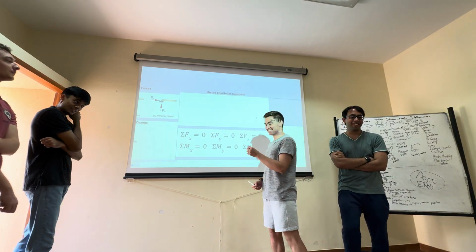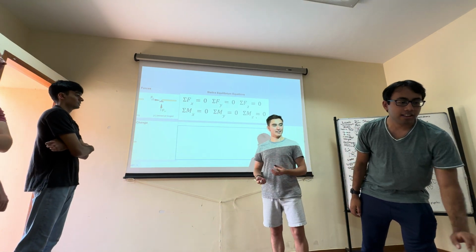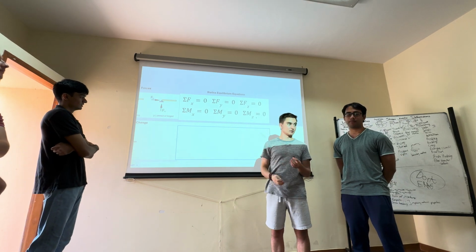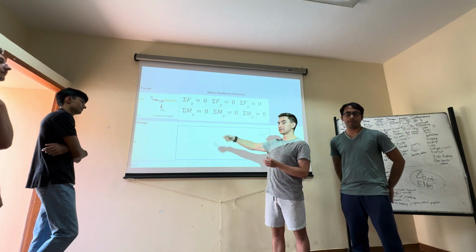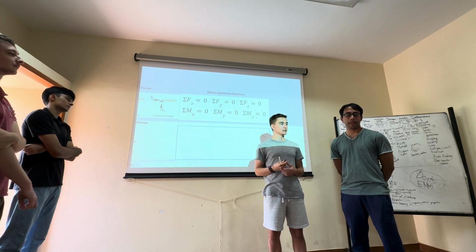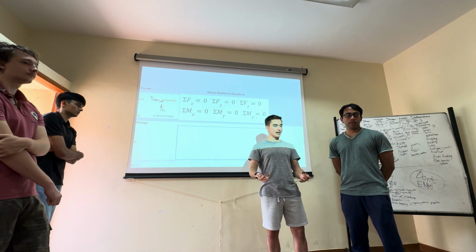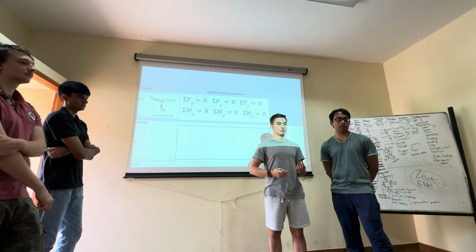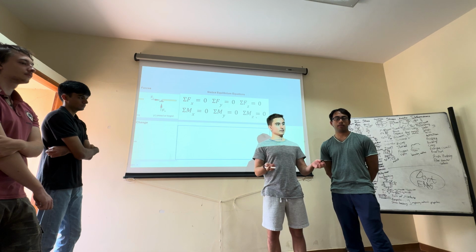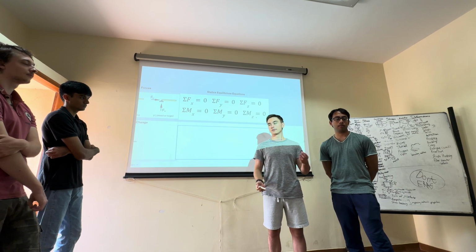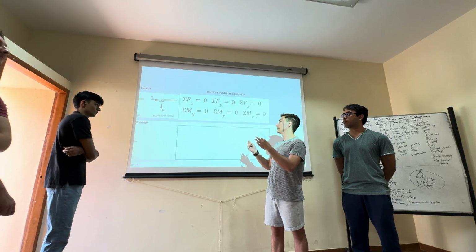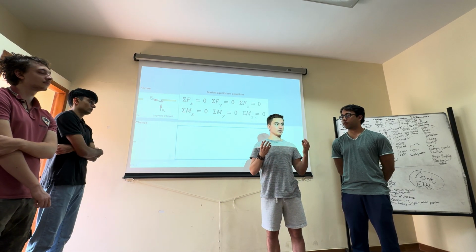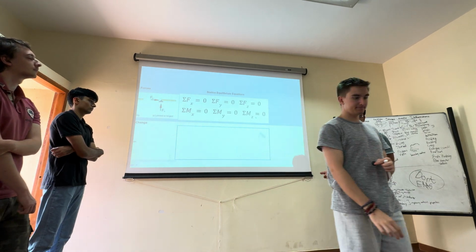Okay, whatever. So when we talk about something being static, it means we have these equilibrium equations. The sum of forces in all directions is equal to 0, as well as the sum of moments in all directions is equal to 0. If all these equilibrium equations don't hold true, then something isn't static, and that's where dynamics comes in. In dynamics problems, maybe some or all of these are 0, but not the rest. For example, if something is pinned but the sum of moments is not equal to 0, that will cause rotation, so it's not really a statics problem. I think that's everything there.